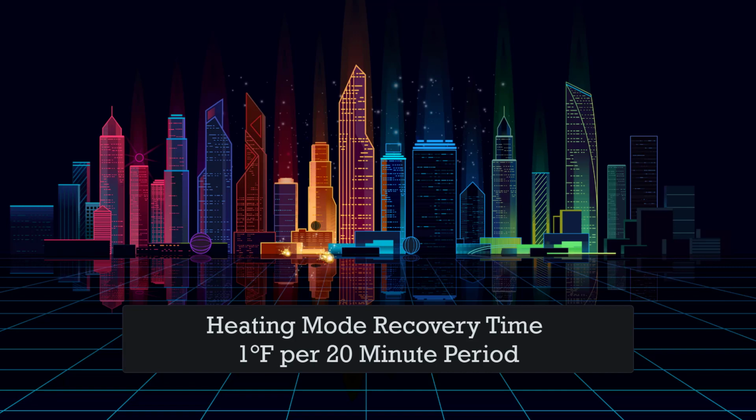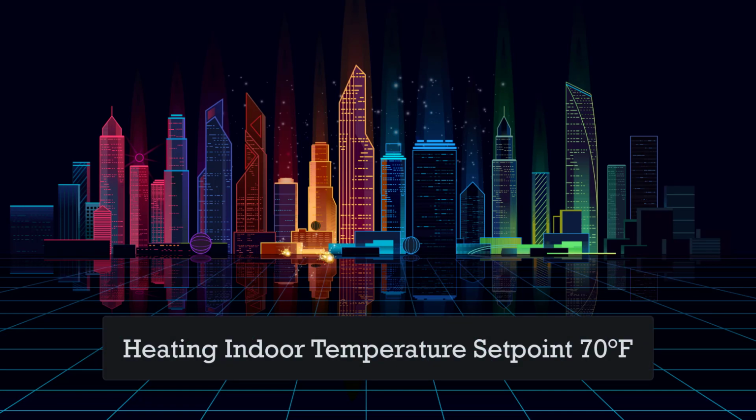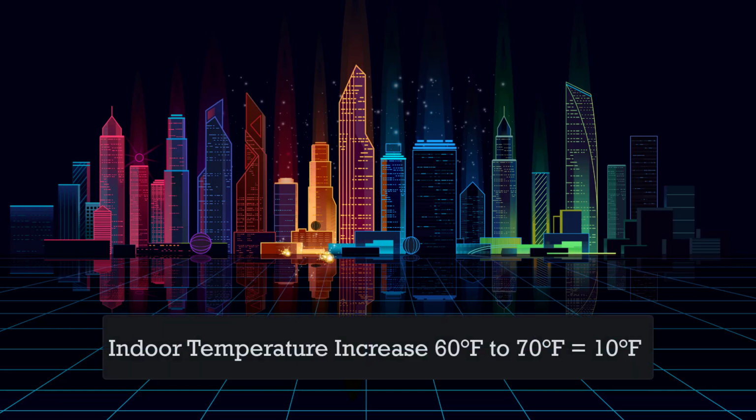In other words, prior to the occupancy period, when the central heating plant starts, it will take an estimated 20 minutes to increase indoor air temperature 1 degree Fahrenheit. If you recall, our heating comfort zone set point is 70 degrees Fahrenheit, and our unoccupied period indoor temperature reset is 60 degrees Fahrenheit. So the indoor temperature maximum range from unoccupied mode to occupied begin time is 10 degrees Fahrenheit.